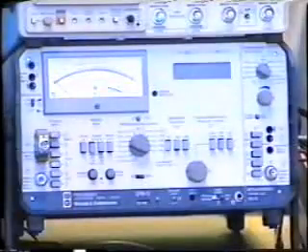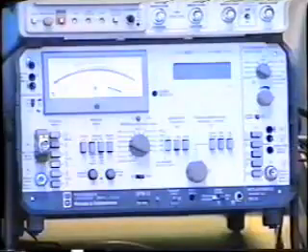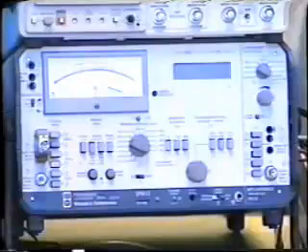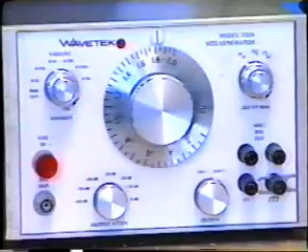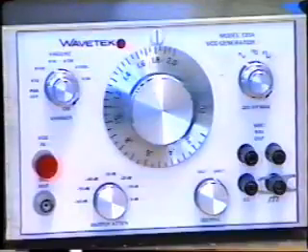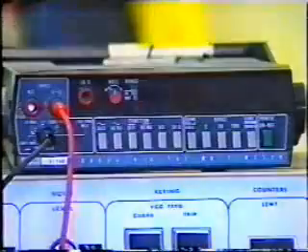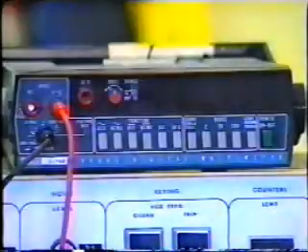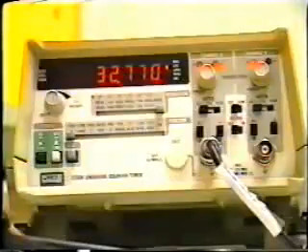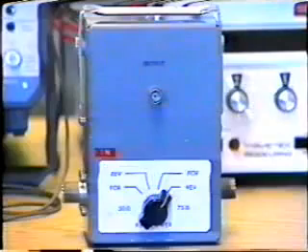You have observed that specific test equipment is required for setting up carrier systems. The essential devices are the frequency selective voltmeter, which registers the signal at the selected frequency only and disregards all other signals; the signal generator to provide a test signal at selected frequency; the RF voltmeter; the frequency counter; and the reflective power meter.